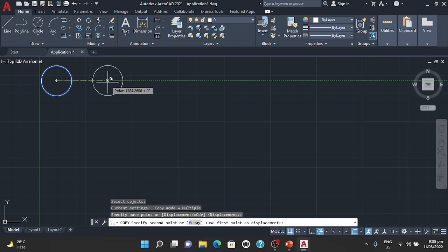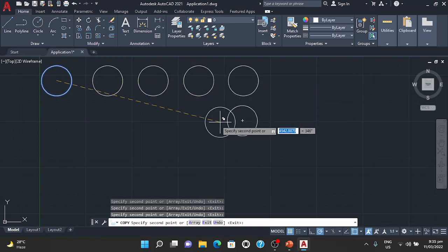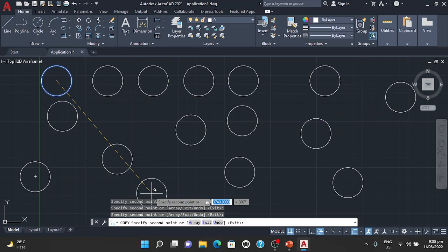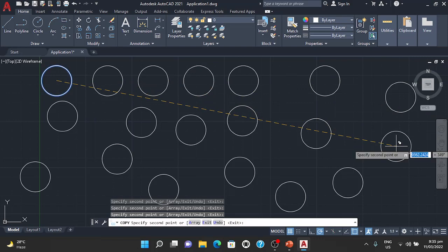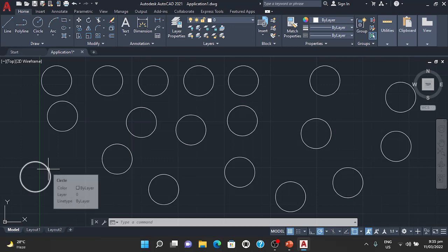So, for example, I created the circle. Automatically, the copy command activates multiple copies of circles. For example, I want a circle at this part. So I could create multiple copies of circles, some aligned and some not. So let's press enter. Overall, we have here 3, 6, 9, 12, 15, 18, 19 circles. So in the application of pick, we could pick circles by just clicking them.